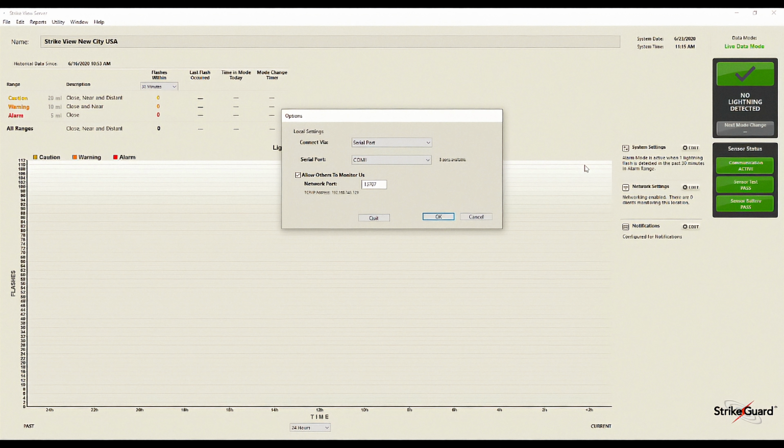The fiber optic cable that comes into this computer is coming in on one of the COM ports. It's either coming in via USB to RS-232 adapter on a USB port, or it's coming in via serial port, which is a 9-pin connection to the back of your computer.